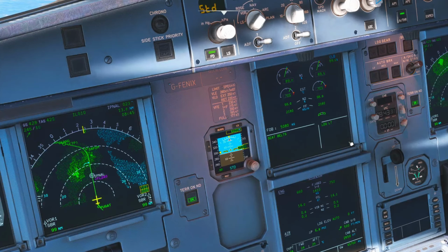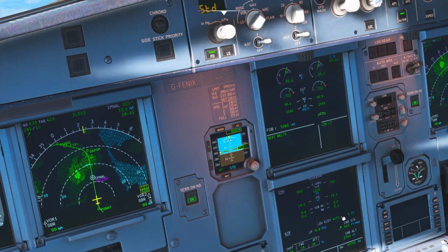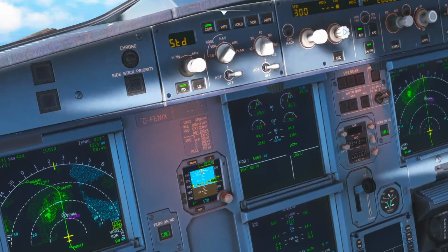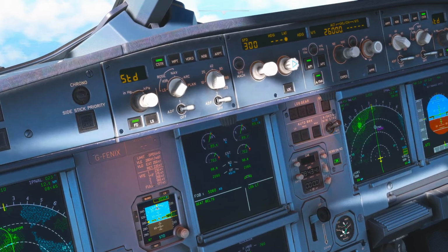If you are flying manually at this point, be careful: you need to use pitch control to manage airspeed. The thrust system is not holding the airspeed for you in this mode. Use vertical speed mode if you want your thrust to maintain speed for you.